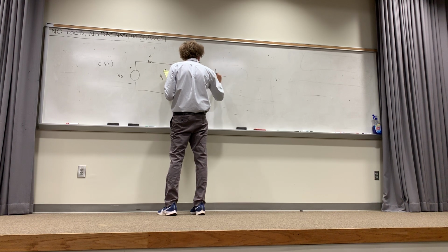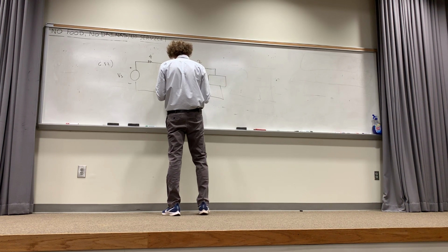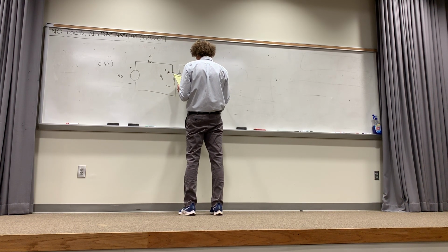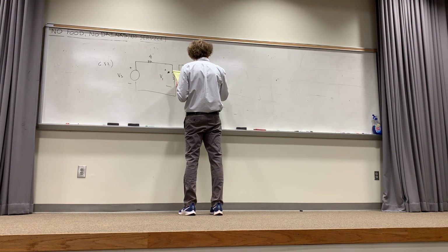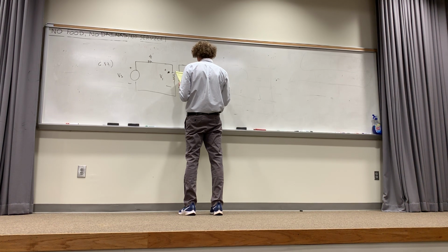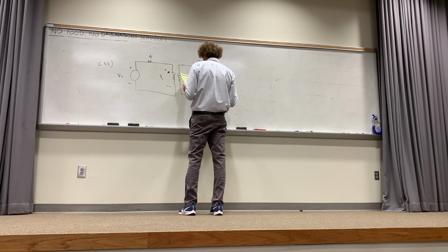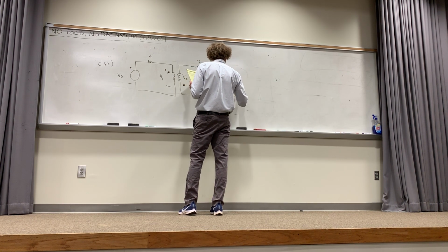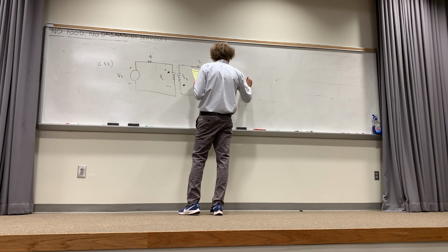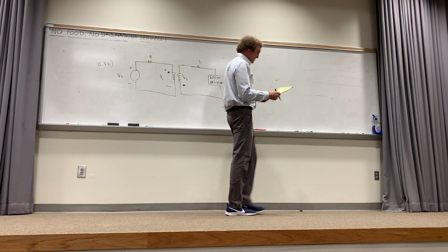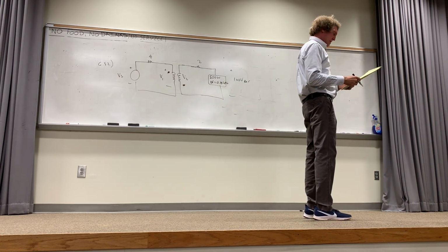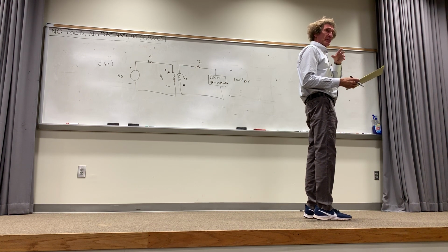And then you have a load here, but this load is in power, so it's saying it's 500 watts. And the power factor is equal to 0.8, lagging. And there's a voltage, plus to minus, of 100 volts RMS. This is the difference. Everything else has been in peak value. Now it's RMS. Do you all understand?